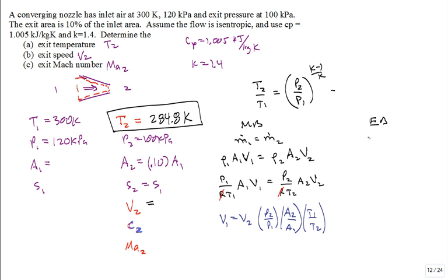Energy balance equation. We start the energy balance equation, which is H1 plus KE1 equal to H2 plus KE2. True? And then we manipulate: H2 minus H1 is equal to minus KE2 minus KE1. You don't need to put the minus sign in there. I mean, you just need to be algebraically correct. Okay, I put C sub P, T2 minus T1. Why did I do that? I was told to. It makes it so I can do things analytically.